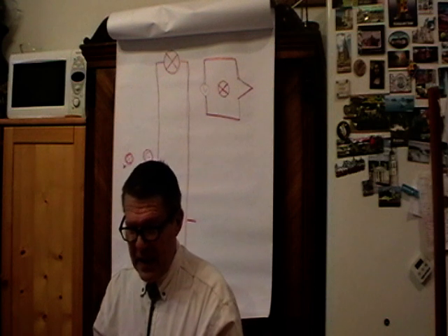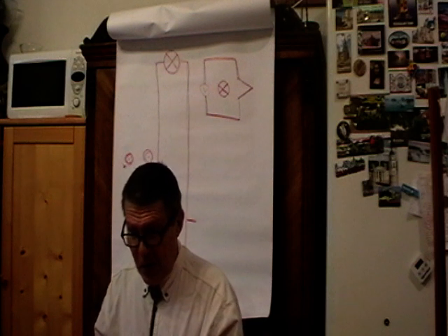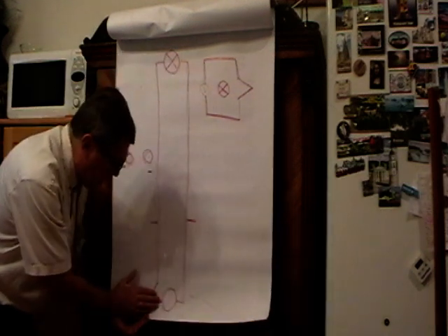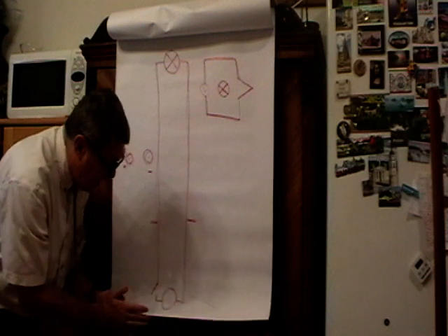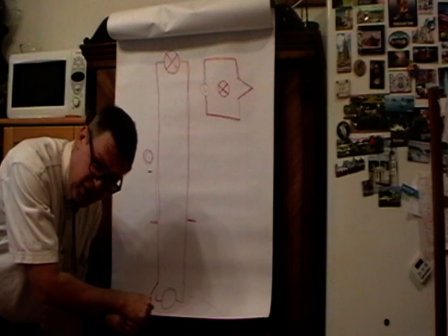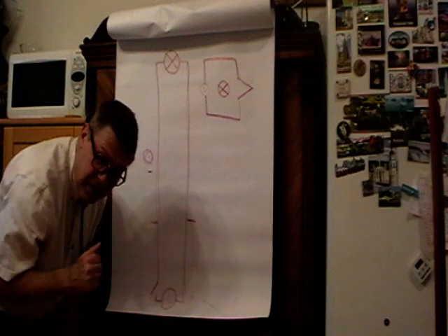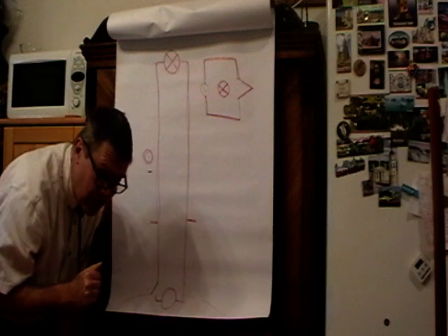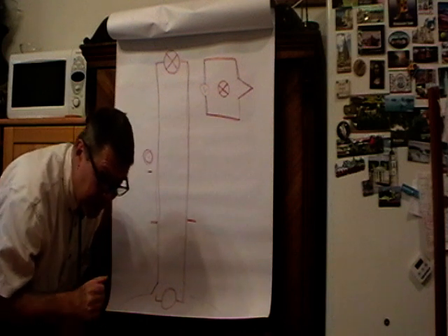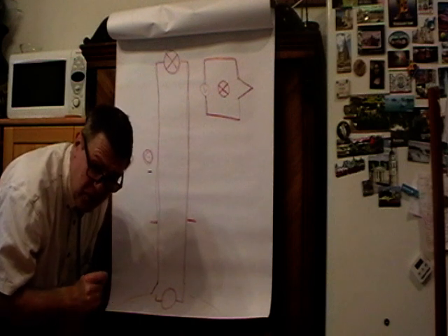Now, to begin to make the thing interesting, we would have to switch the power on, the switch which is downstairs. So, okay, we have switched the switch on, and that means that the source has imposed a voltage on the line, just here. But remember, there is a finite velocity with which any information or mass could propagate.